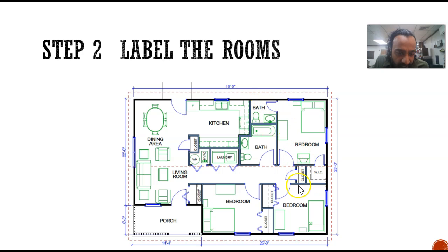What about closets? If the closet is part of the bedroom, for example here, and it's facing the outside, we should heat it. But this is a utility closet, so we do not need to heat that closet. Actually, it is a walk-in closet, so probably you will heat that. You include that wall inside the room heating, but you do not include this volume when it comes to infiltration. So when you calculate that wall, you will go all the way with the closet, because the closet is actually going to gain some heat, and that heat will be coming from the door over here.